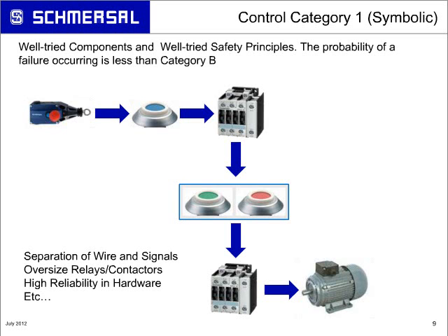If you have a 5 horsepower motor and you put a 5 or 6 horsepower rated contactor in there, you're close to the maximum load requirements or capabilities of that relay or contactor. So your chances of arcing are much higher being close to that maximum load. Doing things such as doubling the size, put a contactor that's rated for 10 horsepower, it has a much higher